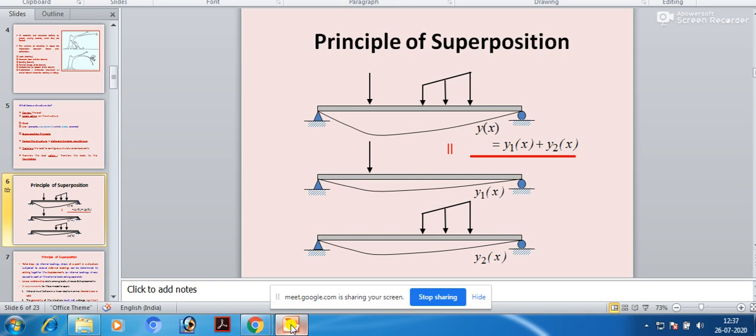So you see, this beam, when subjected to a point load and a uniformly varying load, you are basically summing it up. You calculate the deformation because of this point load separately. Do you remember Macaulay's theory? Last semester we studied Macaulay's theory, deformation calculation. You remember? Sir, EI d2y/dx2. Yes.